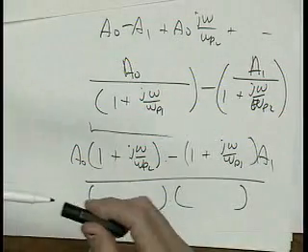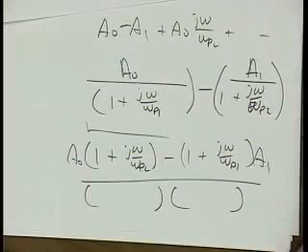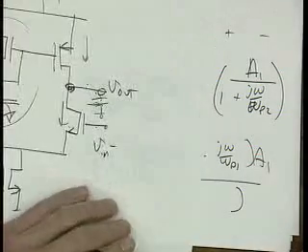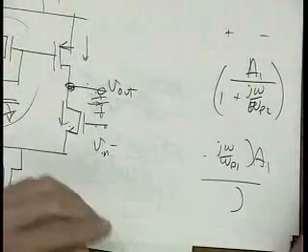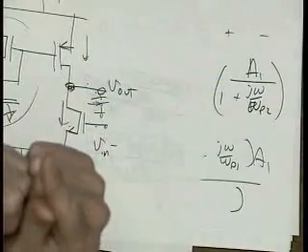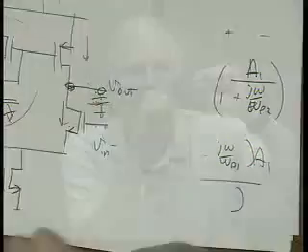Okay. What if the mismatch is from a process? Does that zero come down low enough? It's a pole-zero pair. So if it gets small, then it's just a little doublet that happens, and they compensate out as soon as you get far away from it. But it can. Yeah, process variations are another place where you get some trouble. Since it's not a very big error generally in the process, it's not a big split.